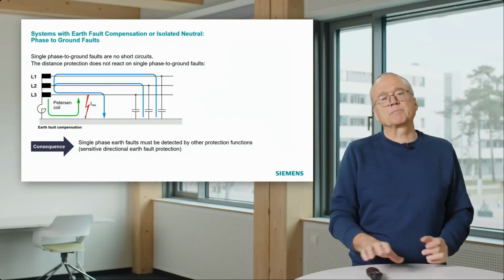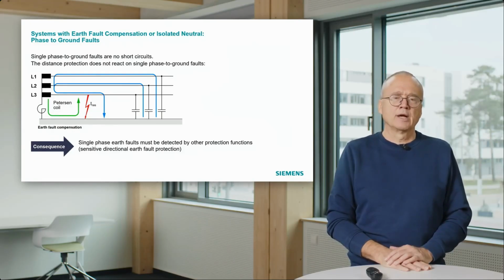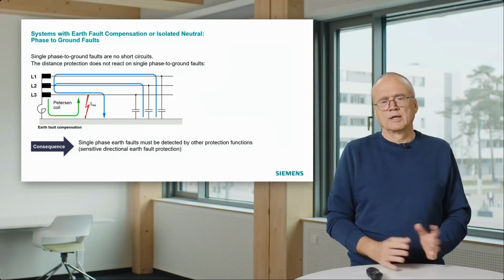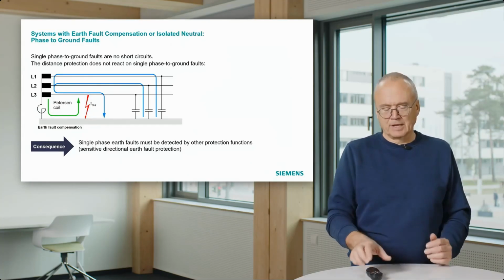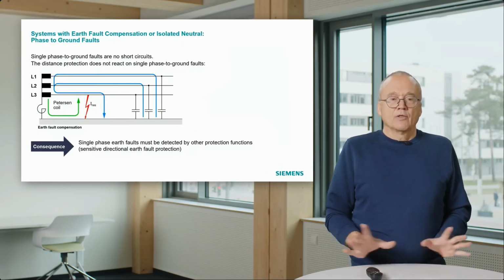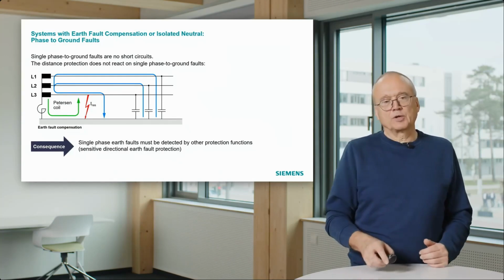Theoretically it's possible, but practical experience shows that these equations you obtain are pretty unstable, so the result was distance protection cannot be applied to catch these faults. That means we have to focus on the other fault types.